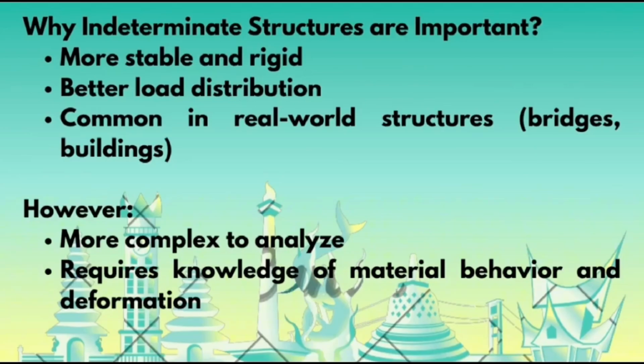More stable and rigid. Better load distribution. Common in real-world structures, just like bridges and buildings. However, more complex to analyze, requires knowledge of material behavior and deformation. Because of their stableness and rigidness, indeterminate structures are important. They also have much more load distribution and are common in real-world structures, for example, bridges and buildings. However, indeterminate structures are more complex to analyze, and in order to analyze those, you need knowledge of material behavior and deformation.